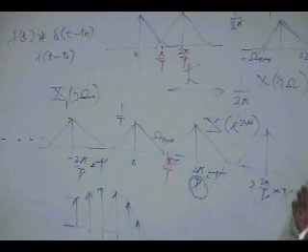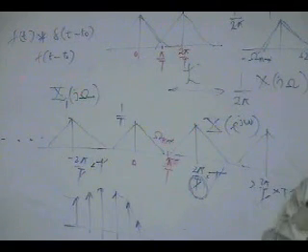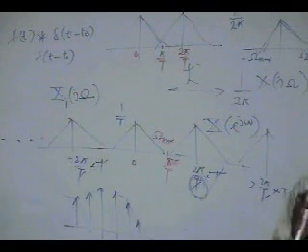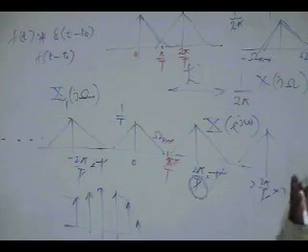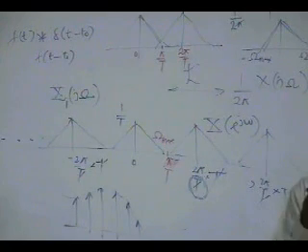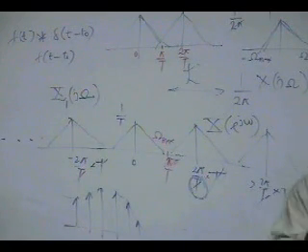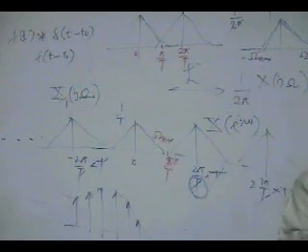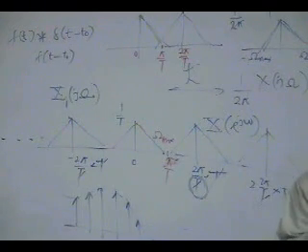Okay, you don't have any control on the signal spectrum because that is your input signal. You have to sample it. The only control you have is on capital T, that is, how fast should you sample? You cannot say I'll cut it down because I don't have a fast enough A to D converter. That will corrupt your signal.